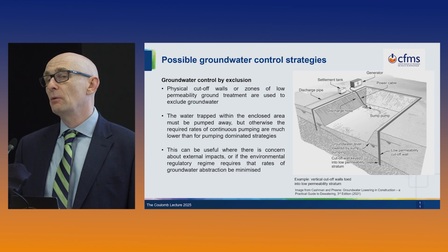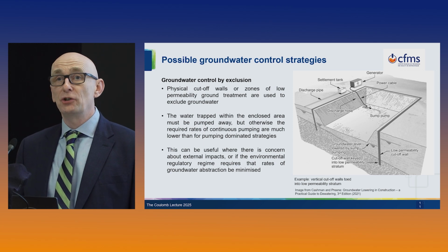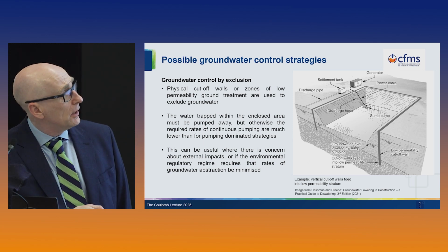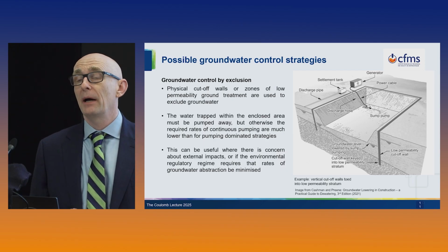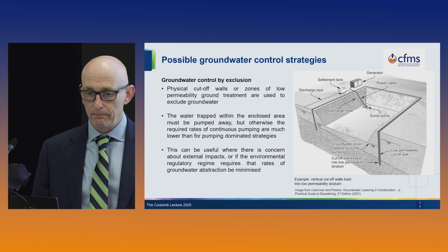So it has the advantage that we're pumping much less water, and also it has the general advantage that we're probably going to be having a much smaller lowering of the water table on the outside. So if we're worried about impacts, it can have its advantages.